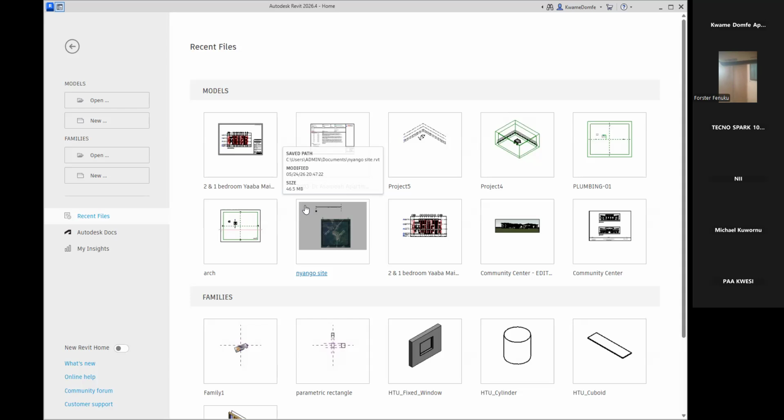But if you do not put a cost to it, then there's no way when the quantity surveyor loads the Revit file into his software, he can get the cost value. It won't be there. So, before you can add the cost, which is the 4D, you must understand the 3D model, then you can add on the 4D.